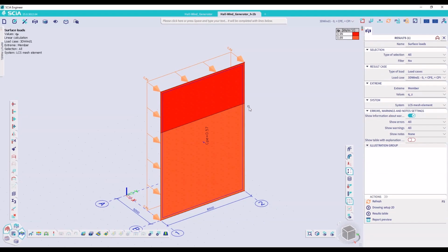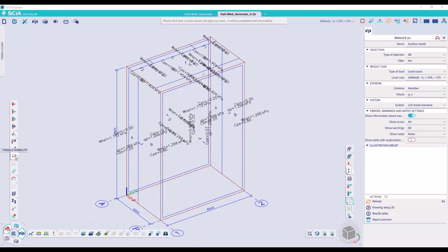Below the height, which is equal to the width, we find a value of 0.89 kilonewton per square meter. Above that, we will find 0.99 kilonewton per square meter for the zone. You will also notice again that the load was still uniformly shown. So this is the way you can evaluate this.